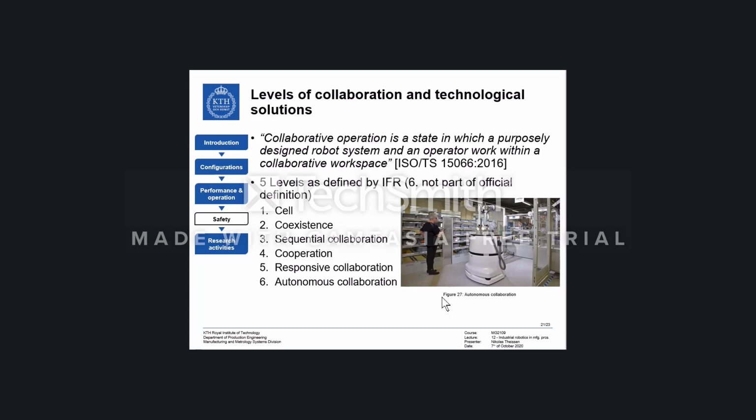And for all the categories 4 to 6, the additional safeguards that one will find in addition to the already named presence sensing devices are force torque sensors that identify the force that is being exerted by the robot onto its environment, or torque sensors which identify how much torque is being needed in the joints, and if there is a deviation between the nominal required amount of torque in order to fulfill a movement, identify the contribution that comes from the human, as well as close proximity sensors such as contact sensors in order to deactivate the robots.